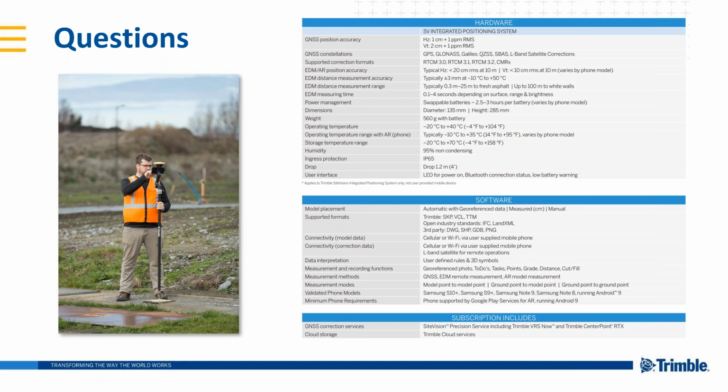You can't sideload a model and view it when you're out in the field, and that's because as the model is downloaded from Connect to the device, there's a little bit of processing that goes on that lets SiteVision work with the model.